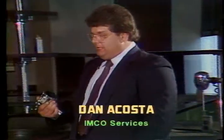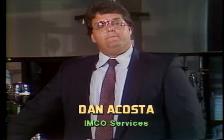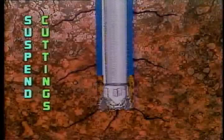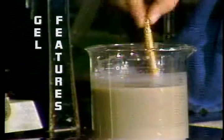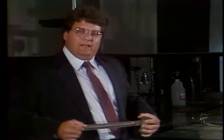Bentonite is our most common type of mud additive, and it's mixed with fresh water to make a freshwater mud. Remember all of the characteristics in Part 1 we were looking for? Fluid enough to scour the bottom of the hole, thick enough to carry the cuttings to the surface, good fluid loss control characteristics, and the ability to turn from a liquid to a gel and back again easily. Well, bentonite in fresh water does all of these things. It makes a good all-around mud.